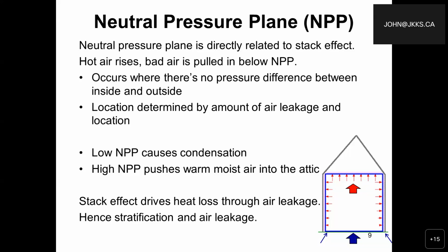So this is what is known as the stack effect. It drives the heat loss through air leakage, hence stratification and air leakage. As we know, as we stand on a floor in the winter, it tends to be maybe a little cooler around our ankles than perhaps around our head or towards the upper part of our body.